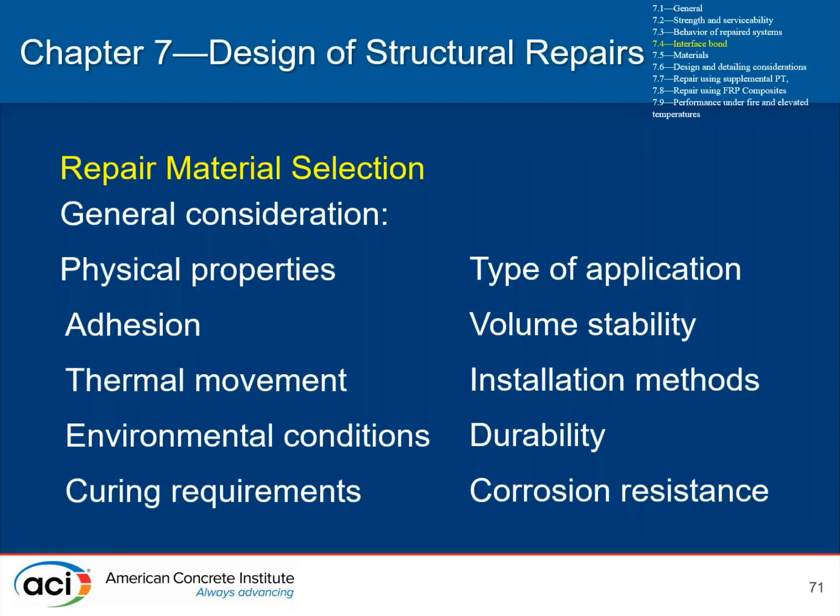Again, I touched on this a little bit, but repair material selection is very important, and the physical properties are important with respect to the durability, the thermal movement of the repair material, the volume stability with shrinkage, etc., but also the adhesion or how well it adheres to the existing structure is very important.